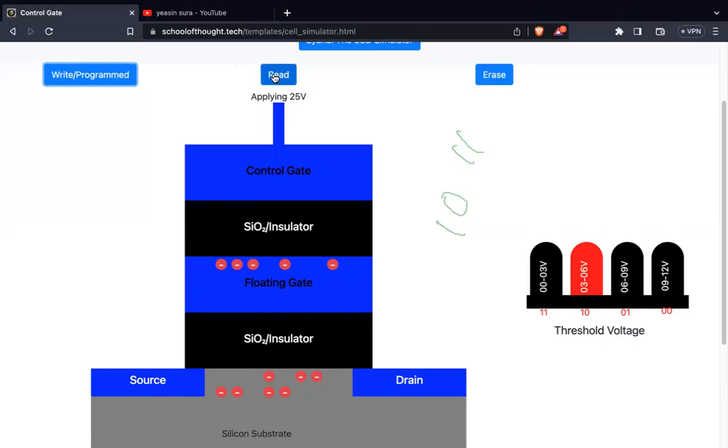Now if I click on read button again, it will start from the beginning again. 2.5 volt will be applied, and as you can see, electron will not be able to flow from source to drain. Again, we will start to apply 5 volt, which is the second threshold voltage. As you can see, electron is not able to move from source to drain. Again, we will apply 7.5 volt, and now you can see the current started to flow from source to drain. Now we can say the stored information is 0 1.